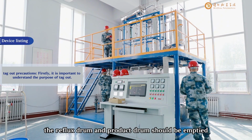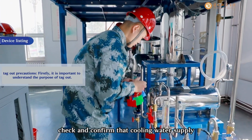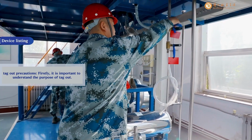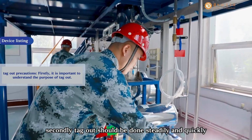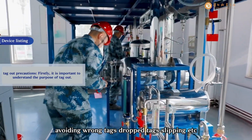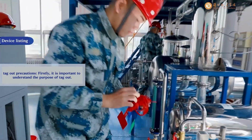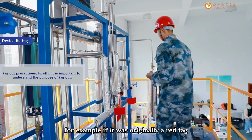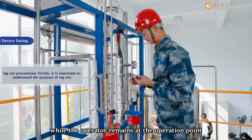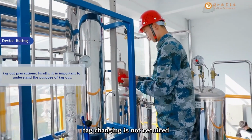The reflux drum and product drum should be emptied before tagging. Check and confirm that cooling water supply is available before tagging for cooling water valves. Secondly, tag-out should be done steadily and quickly, avoiding wrong tags, dropped tags, slipping, etc. Finally, regarding tag changing. For example, if it was originally a red tag, and the valve needs to be opened briefly while the operator remains at the operation point, tag changing is not required.